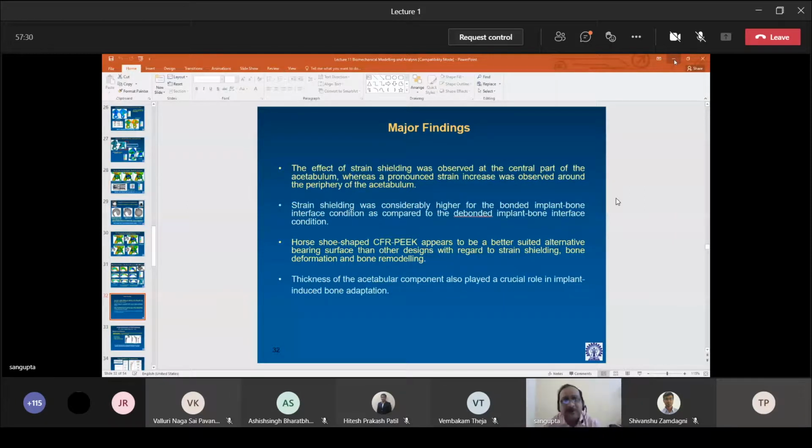So you have to be extremely careful. This is called the partial volume effect. The partial volume is located in no man's land, and you can make mistakes by picking up erroneous CT gray values, which will influence your E modulus. We have seen that.